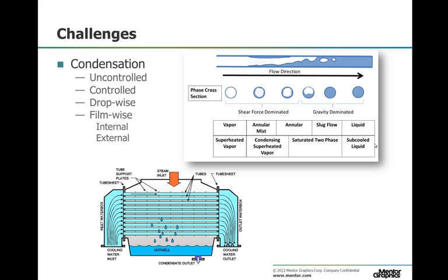Uncontrolled condensation occurs in systems when the temperature of the vapor is reduced because of heat loss to the surroundings, until small liquid droplets begin to form on the surfaces. As more and more droplets form, they merge and begin to flow along the bottom of the pipe. This buildup of liquid begins to affect the flow of the vapor and can have damaging effects on the systems. In cases of vertical or inclined piping, the liquid will flow in the reverse direction of the vapor or at a faster rate if they are moving in the same direction. Again, this slip flow also has an effect on the flow rates and pressure drops in the systems. Mitigation components such as steam traps will also need to be provided to allow the draining of the condensate out of the system.